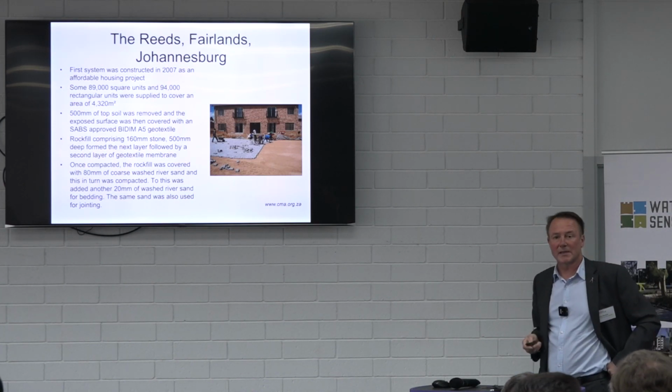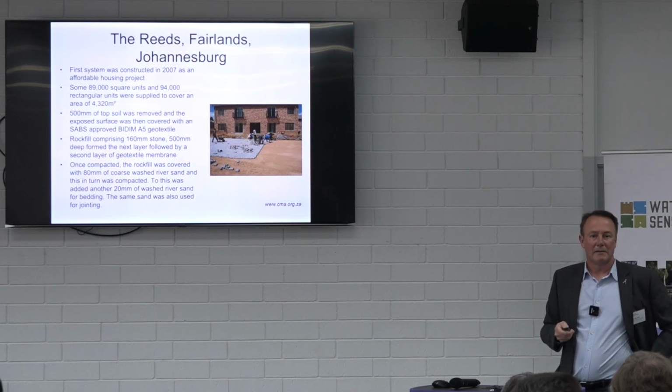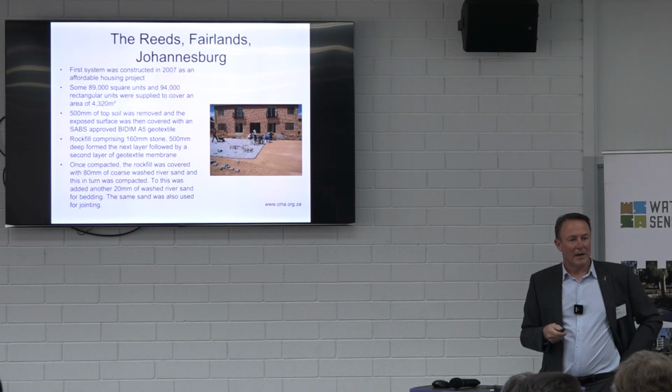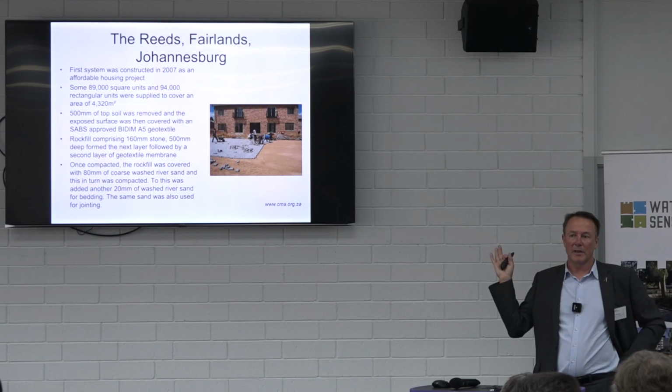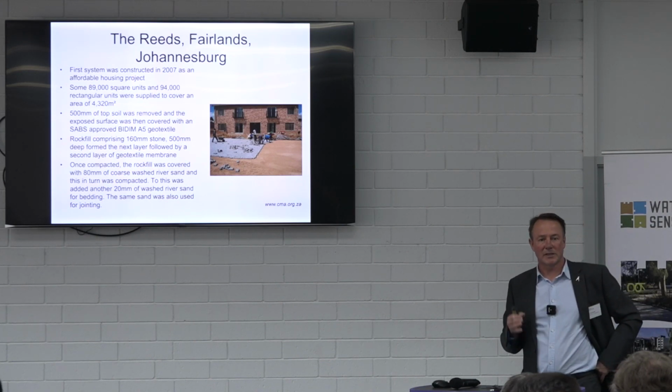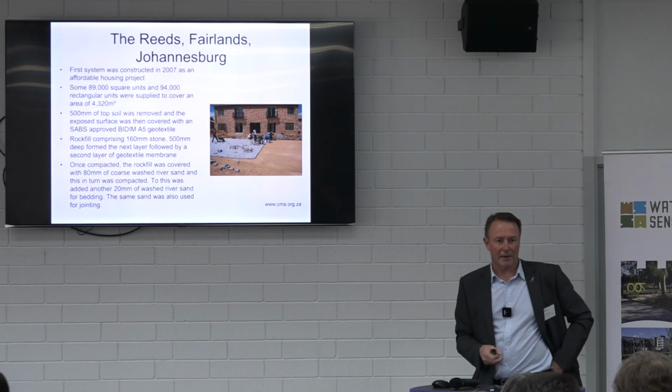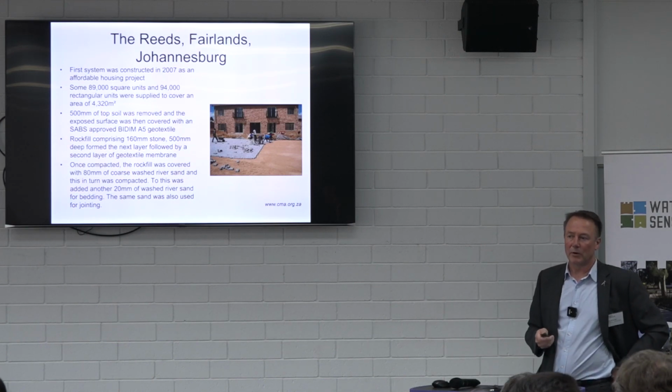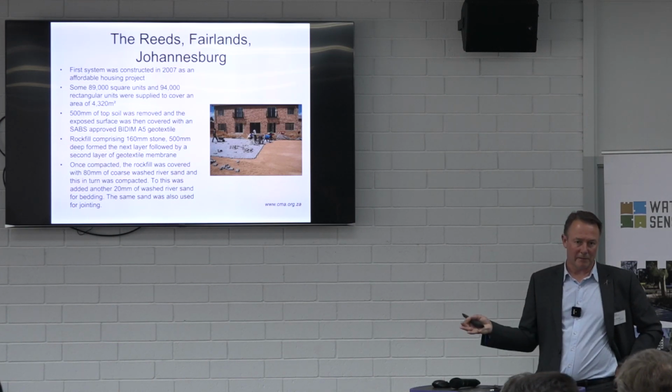And look at that practice, bedding it on sand. That's what I was telling you before. Again, that will clog within a year. You bed permeable pavers on sand, it will clog within a year. Okay, 2 to 6 mil gravel, well designed, 25 years.